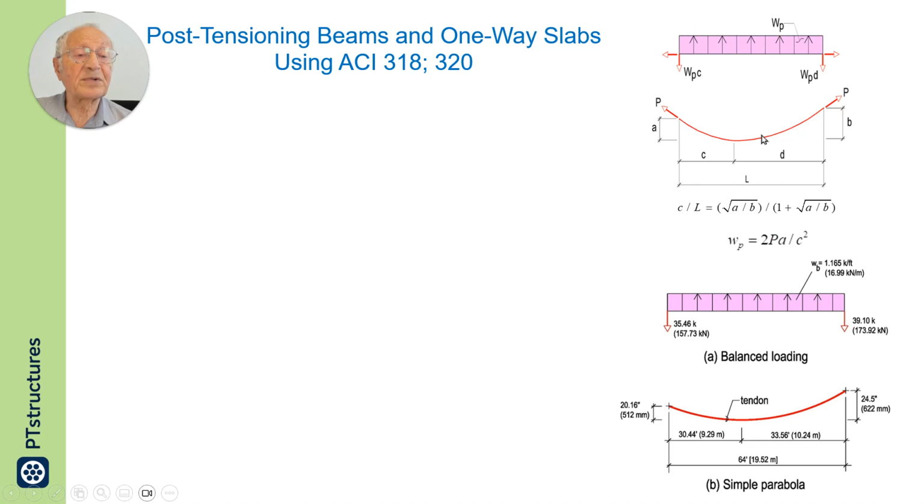I use simple parabola, and for simple parabola, the relationship is given here. The force of the simple parabola is axial, downward at the end, and upward, assumed uniform. In reality, it is very close to uniform, but for calculation, we assume uniform upward force.